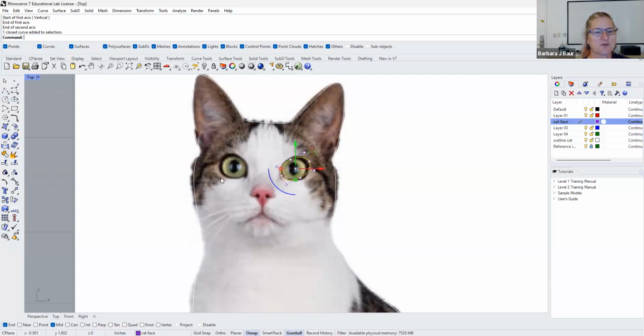So suppose I just wanted to create another one just like it. I can use another command called mirror, M-I-R-R-O-R. Okay, I hit enter, and I'm going to copy this, yes. And so it wants the start of the mirror plane. So I'm going to go like this, and I'm going to just wiggle this line around so I get the eye sort of where I want it.